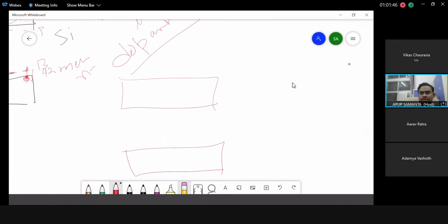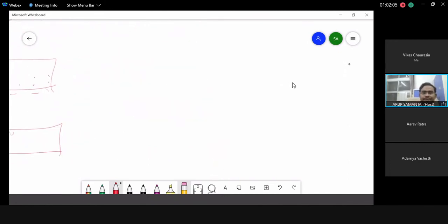Where one type is N-doping in silicon. So this N-type doping in the silicon has higher electrons in the conduction band level. You have more electrons in the conduction level than holes. This is called N-type material. You have the other type where you can dope it by boron. So this level is there, so it can create additional holes here than electrons. So the number of holes is higher, positive charge is higher in the system, and this is called P-type material.